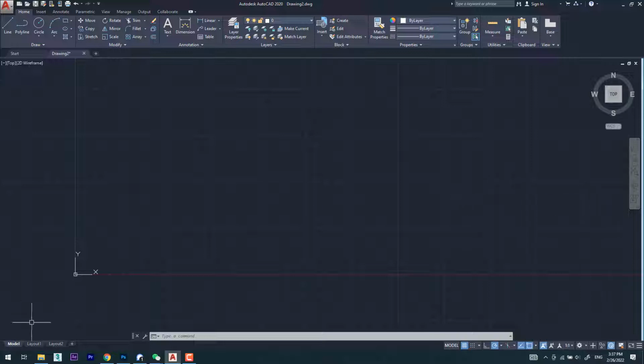Okay, do I have to start every time from the zero? No, you don't have to. You can start from anywhere in this drawing, because from AutoCAD we'll be using just the walls. We're taking the walls, we can move them to 3ds Max, we can adjust, we can relocate the CAD file over there. But for your understanding, it's necessary to know how the x-axis and y-axis work, where the x is negative, where the y is positive. Everything you should have in mind.